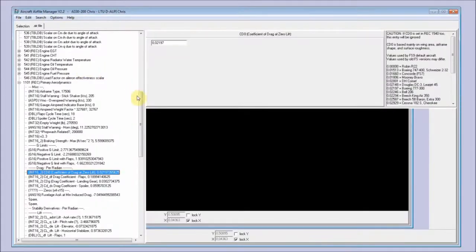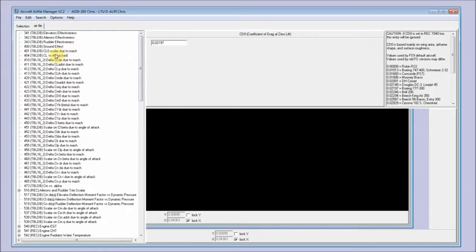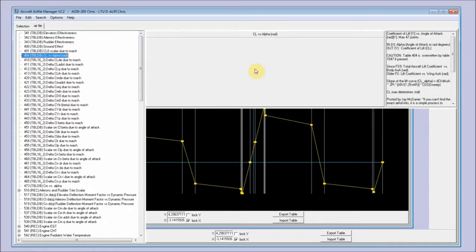So how did I start at the flight model? The most basic value or curve is the CL versus alpha curve, which simply represents the lift coefficient versus the angle of attack. And I simply adjusted that by the assumption that at a typical cruise, let's assume around 200 tons, the pitch is around 2.5 degrees. I saw that on a lot of pictures.